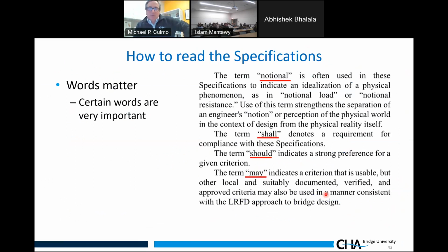We mentioned before the word notional. A notional load is not a real load. It's an idealization of a physical phenomenon. So when you see notional, you have to understand this: the HL93 is not a real truck. It's an idealization of what's actually out in the real world.